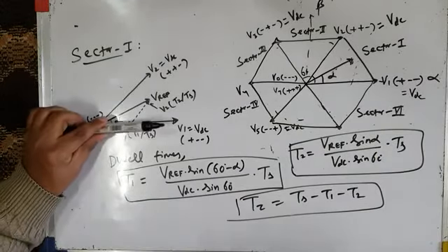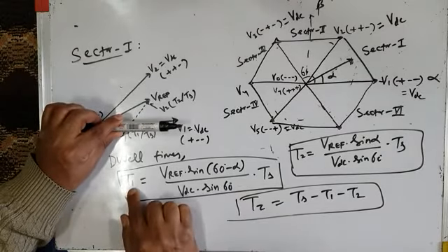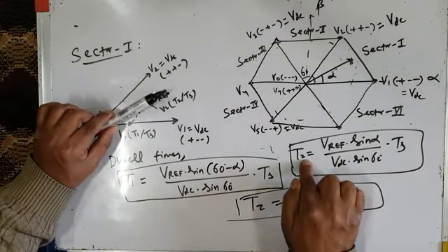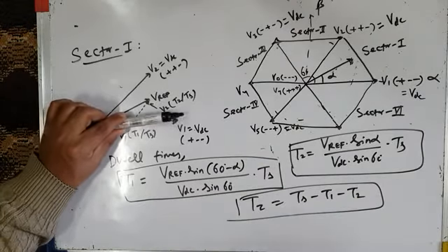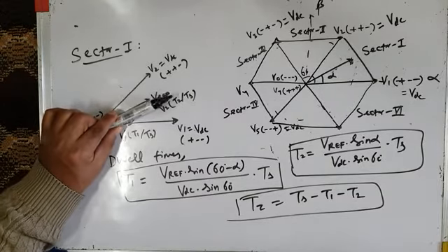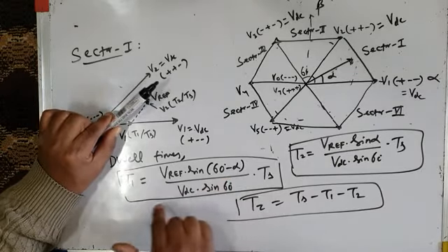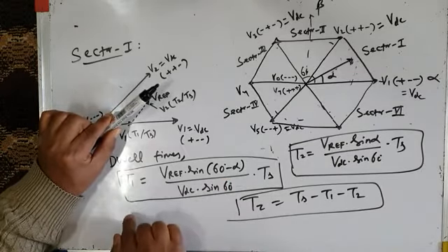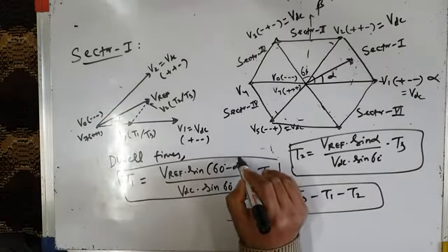So when both voltage vectors are getting applied, V1 for a time interval T1 and V2 for a time interval T2, your reference vector will not be here. It will be somewhere in between V1 and V2, somewhere here. And as it moves like this, alpha increases. And as alpha increases, you can see T1 decreases. You can very clearly see as alpha increases, say, in this equation.